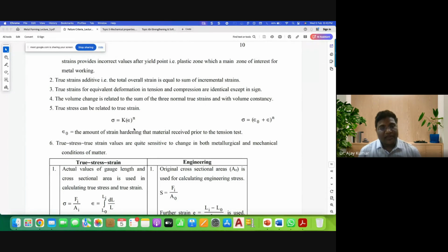When dislocations interact, entanglement will happen. Even dislocation loops we will observe, right? And because of that the material is hardened. So you can see the stress will increase, and then once it reaches the UTS point, the ultimate tensile strength, after that the material's instability starts.